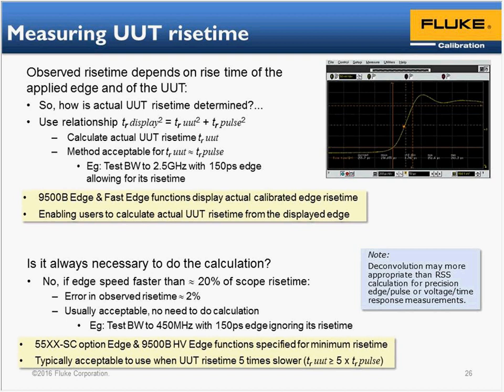However, you may want to do something a little bit more sophisticated and consider the response of the scope to be an actual voltage against time response, not just quantify it by the transition time, but by looking at the actual shape, for which you need voltage time data. A very long data set, actually, for the response, and you would therefore be considering deconvolution techniques to extract the actual response of the scope and the characteristic of the edge that's being applied.